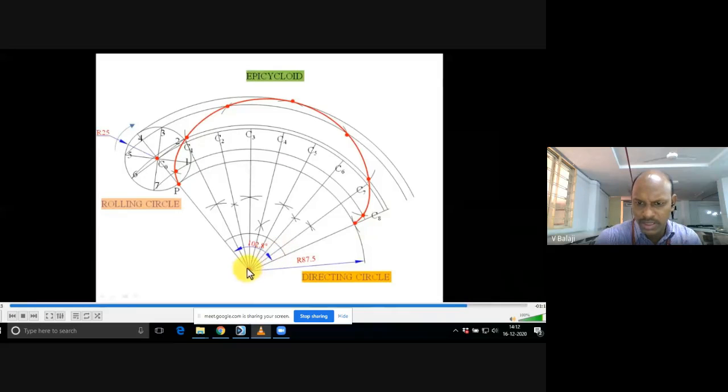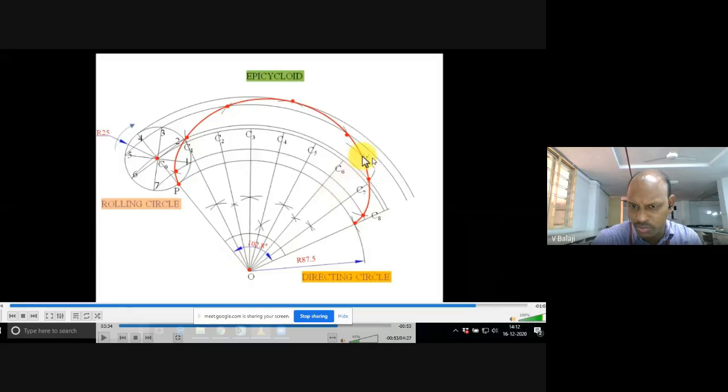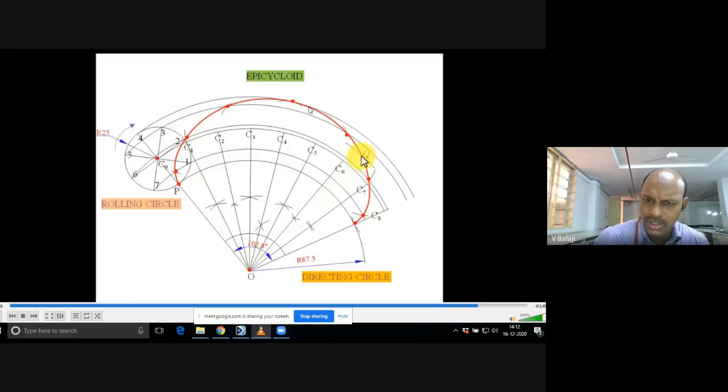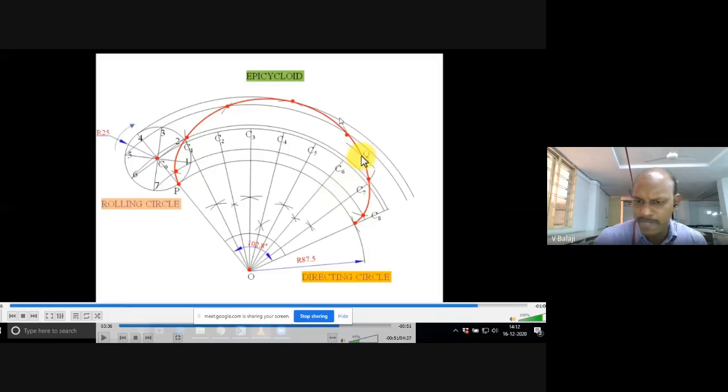Okay, can you do that? So I got this point here somewhere, Q. Are you able to see the Q point? I'm showing you here. Yes, sir. So at that point, I require the normal and tangent. You can also draw Q on the left hand side of the curve; the procedure is the same. If nothing is mentioned in the problem about the 125 mm distance, you can mark any point Q on the curve and draw the normal and tangent at that point.